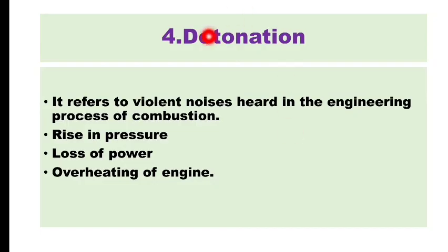Last one and a very simple property of the fuel, the detonation. It refers to the violent noise heard in the engine. Sorry, there is a spelling mistake here. It refers to the violent noise heard in the engine in the process of combustion. The combustion is the process of burning fuel. So while fuel is getting burned, the fuel makes noise, which is called detonation. The detonation will cause a rise in pressure and it will lead to loss of power. Also, if the detonation is in large number, it will result in overheating of the engine. So these are some consequences of the detonation.